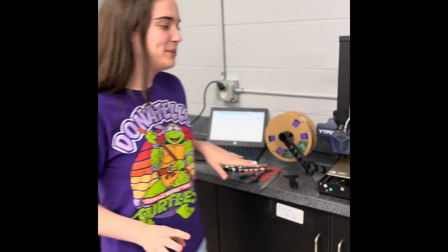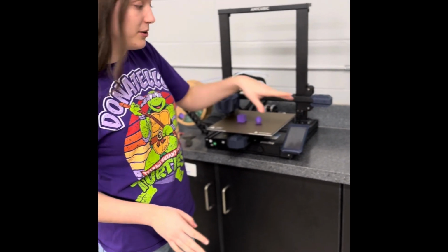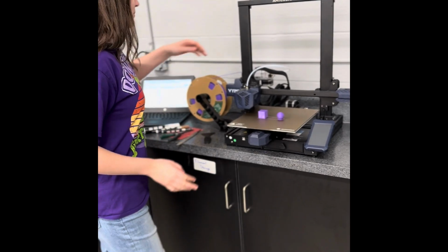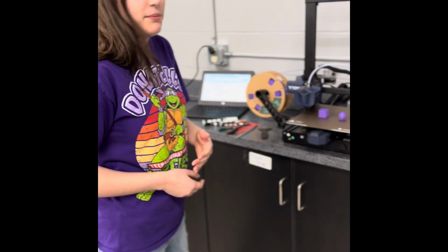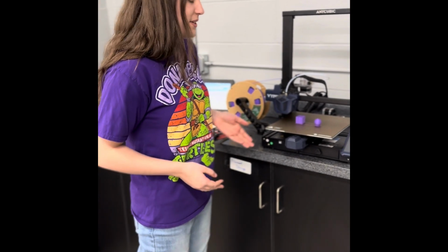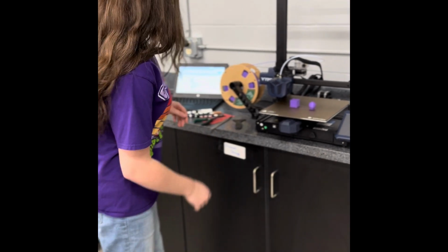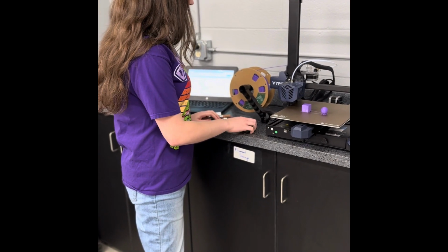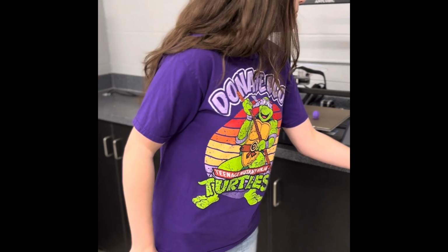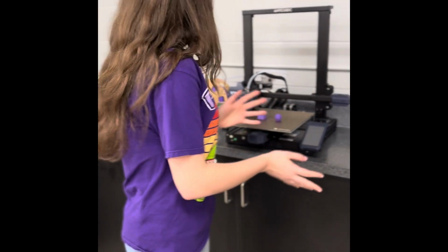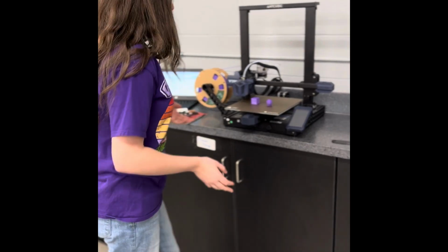Alrighty, so now that we're done printing, we have already turned off the machine, but you'll want to do that, which is the same location back in the back of this. And we will give it some time to cool down so you don't burn yourself because it is rather hot, 195 degrees. And so then what you're going to want to do, we have these nice little scrapers available near all these printers. You find them right next to a printer, maybe on the other side of the printing station.